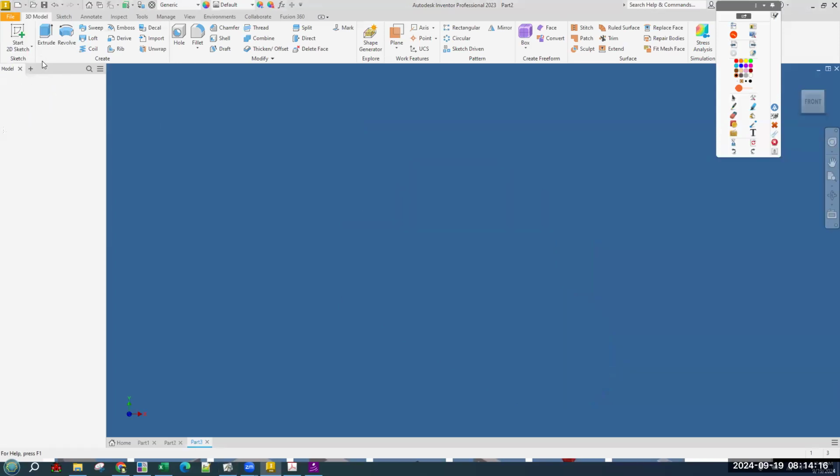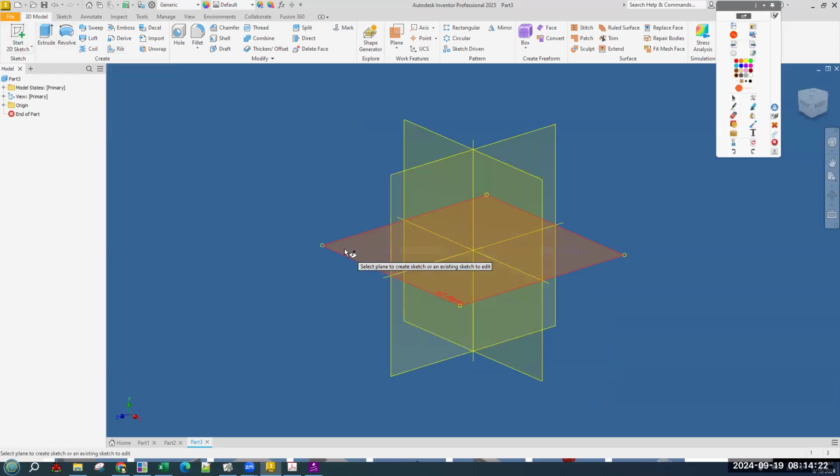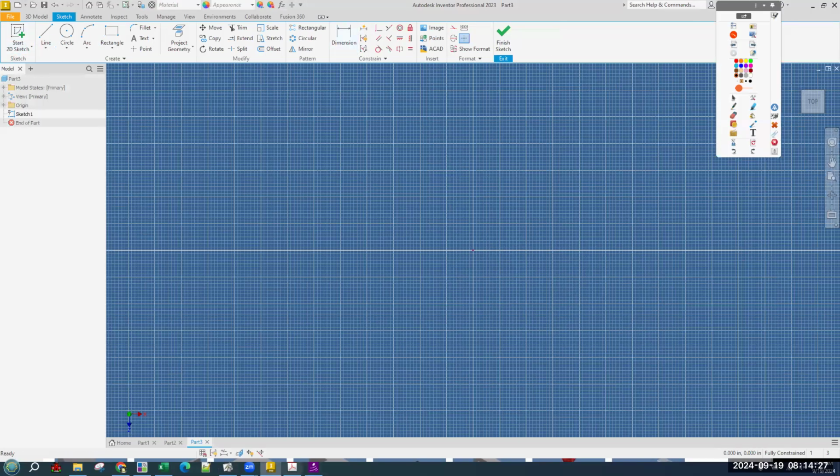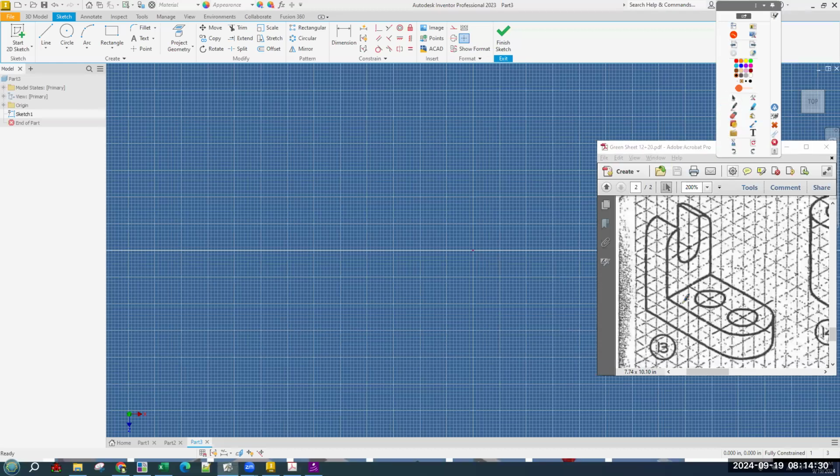First, we need a new part file. And let's start a sketch. We're doing the footprint thing again, so let's start on the XZ. And the footprint of this, if we're going to do sort of the rectangle plus arc, same 4-inch this way. And its distance is 2, 3, 4, 5, 6. It's 7 this way, 4 this way, and arc and extruded 2 up, I think.